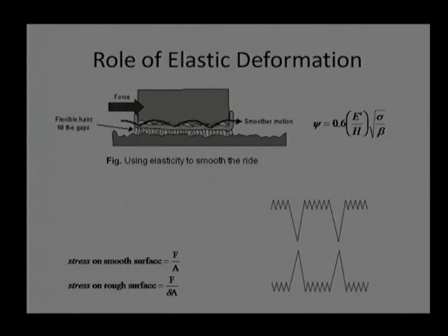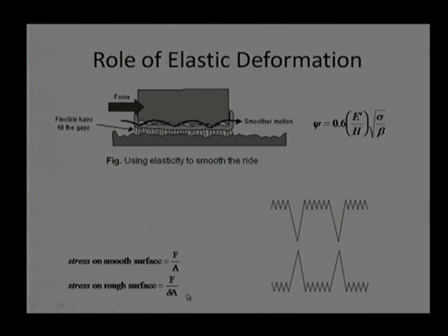Now, coming to the mathematical term, generally we find a stress, linear stress, or uniaxial stress. That stress can be calculated, can be estimated by using force divided by area. Here area in this case is apparent area, which is generally used in mechanical engineering. But when we talk about tribological components, we need to take only a fraction of this area.